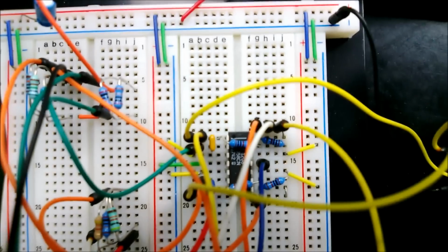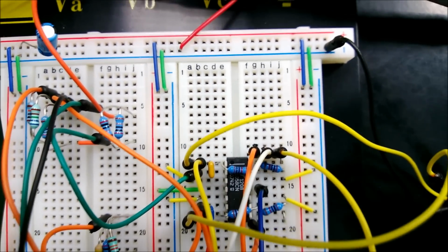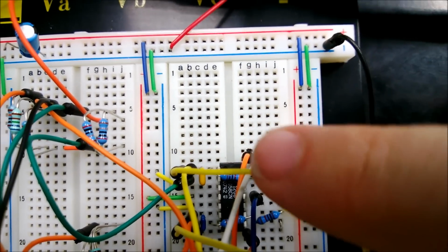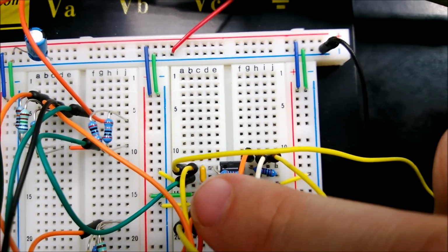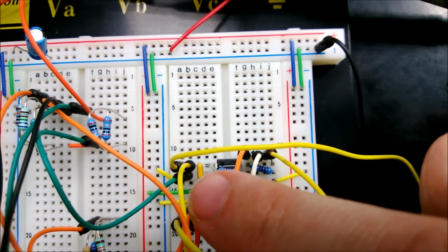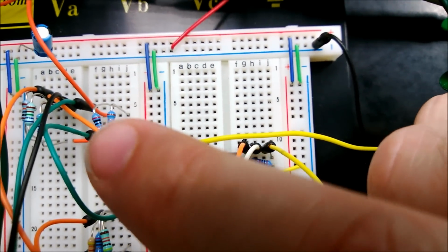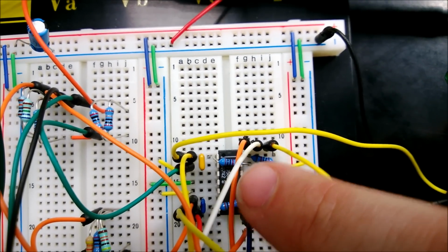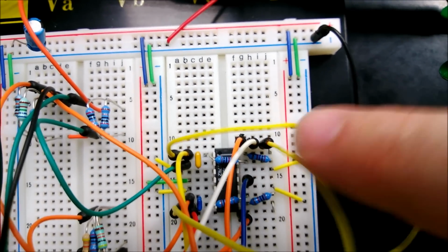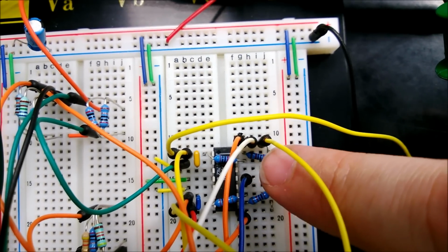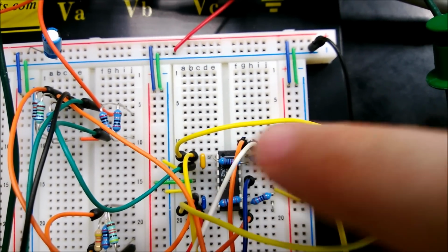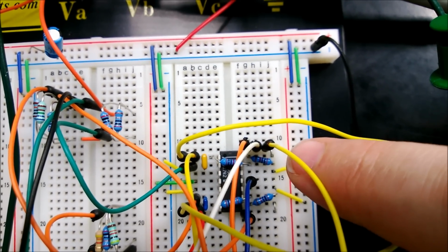In the middle, the part with the capacitor is what does the integrating. It takes all those inputs from the upper left-hand corner and integrates them, and then over here we take that output and invert it. So we have our x and then our minus x as our output.